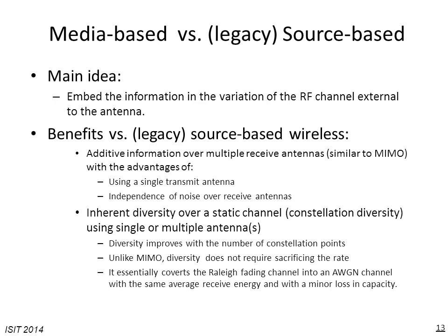When we randomized it, we saw that the outage essentially disappeared. We always had a constellation with 4 points, and the good and the bad channel conditions, which correspond to beams of lower and higher gain, contributed to building a single unified constellation at the receiver. So the concept of diversity and outage essentially changes into a whole new paradigm altogether. The point is that the diversity is built into the constellation structure.